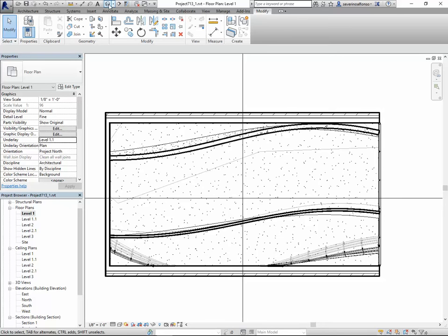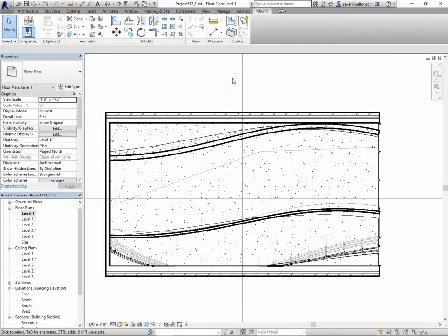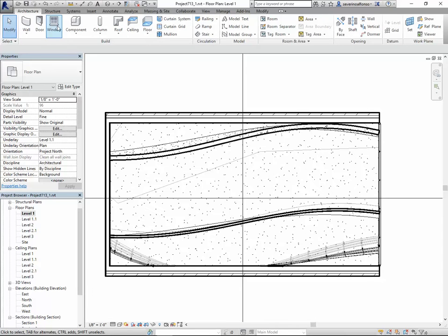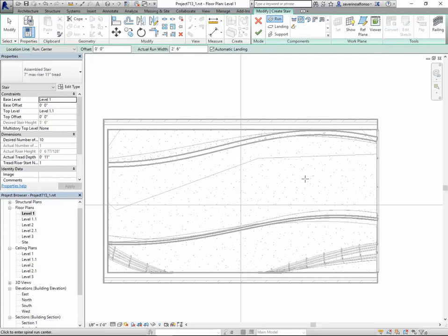So we want to do, let's say, a stair from level 1 to 1.1, from 1.1 to 2. Okay, so you always go to the level and you say architecture, stairs, stairs. I'm going to do a straight stair and then a curved one or something, or a curved one first and then a straight stair. Select the full step spiral stair. I'm going to just go up there and they're going to walk here. I'm going to make them like 2.5 feet, for example. It's a small space and it's kind of like an installation.